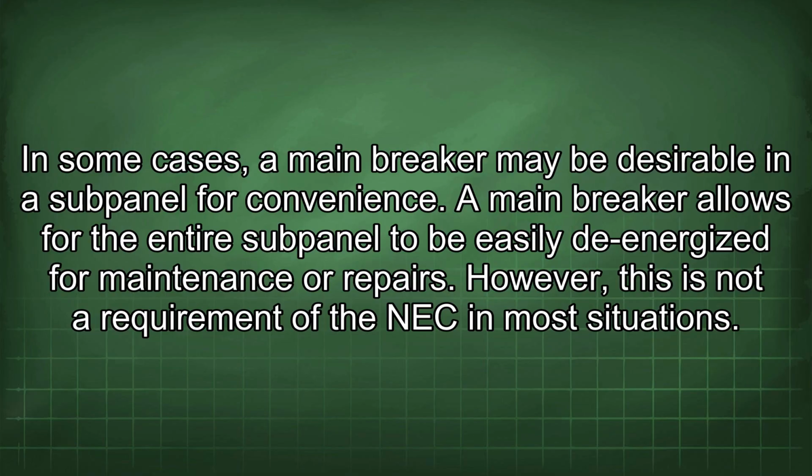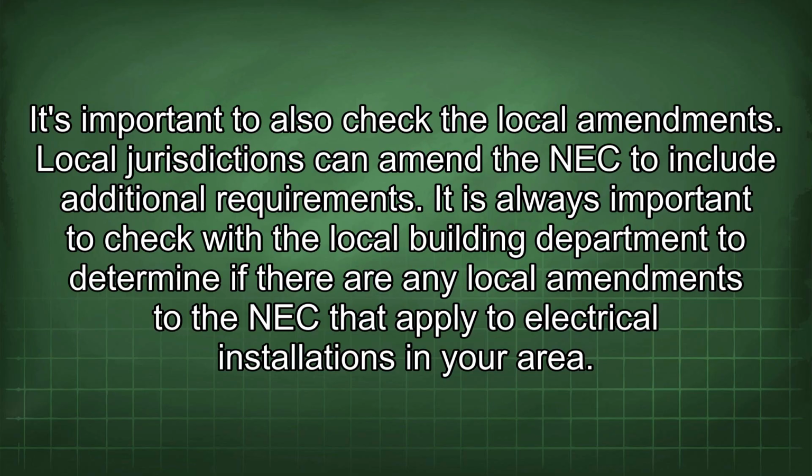A main breaker allows for the entire subpanel to be easily de-energized for maintenance or repairs. However, this is not a requirement of the NEC in most situations. It's important to also check the local amendments. Local jurisdictions can amend the NEC to include additional requirements.